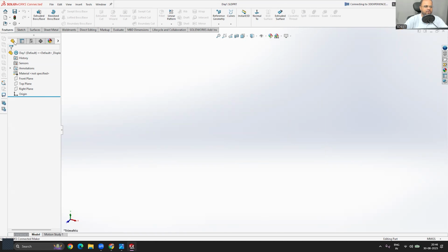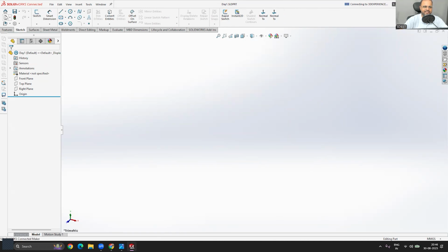Okay, so now these were the options for the settings. After that, we have a few more things in this feature panel, like extrude and revolve. These tools are all 3D tools that we'll be utilizing when we start modeling something, right? Then we have the other section that says sketches. The first section is always common for all the tool panels, but the rest of the tools change based on the tool panel I am selecting.